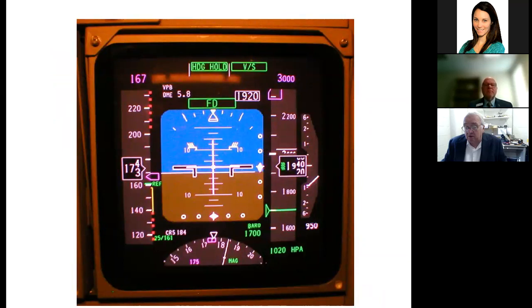Our courses, and I'll tell you more about the course content in a bit, tend to look at the flight deck, or the instruments that the pilot looks at when they're flying the airplane. This is a 757, 767 display. Along here we have airspeed and all the various things that help the pilot manage airspeed. Over here is the altimeter, and over here is vertical speed. Down here is the navigation display, the compass, and the lateral course and heading settings. Right in the middle is pitch and roll, and up here are the various modes that the autopilot is in to fly the airplane.